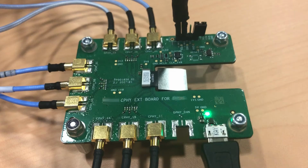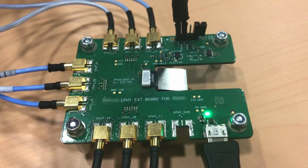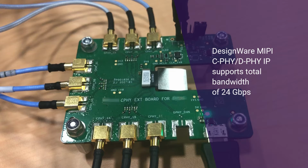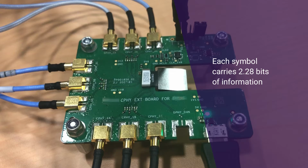Our C-PHY in 12 nanometer is able to recover the C-PHY traffic at 3.5 gigasymbols per second per trio. And in this case, the traffic is coming from a real device. We're talking about one of the most advanced image sensors available today. Note that the total bandwidth for the 3 trios is 10.5 gigasymbols per second, which translates to approximately 24 gigabits per second total bandwidth. Each symbol carries approximately 2.28 bits of information. It's one of the interesting things about the C-PHY architecture.